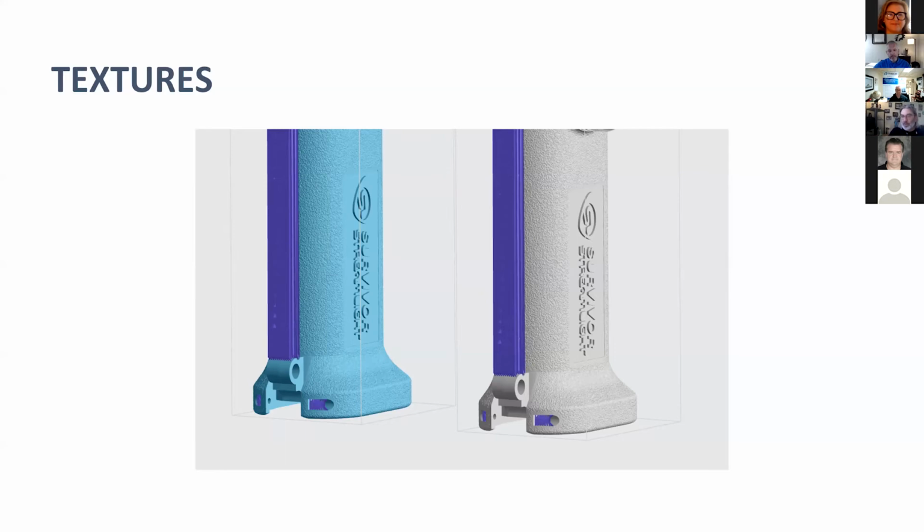But right here, what we're looking at is one of Protocam's texturizing jobs. This image is actually on the printer. You click on the surface of the part, and then you choose the type of texture that you want. You can play with it with depth. You can go higher, lower, cut into the surface, or go above the surface, and you can adjust the tile spread as well to get more pronounced or more subtle.